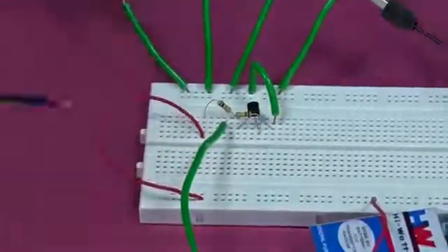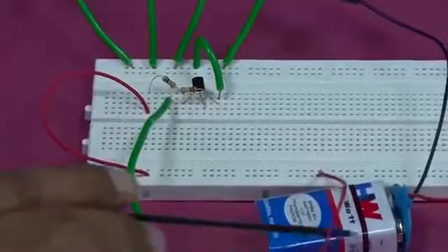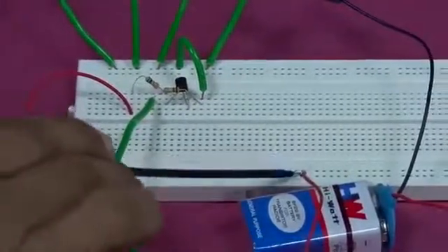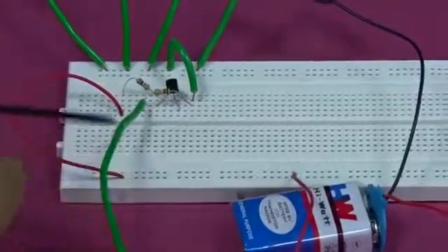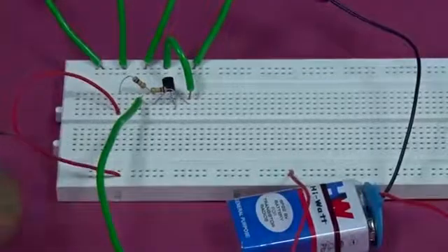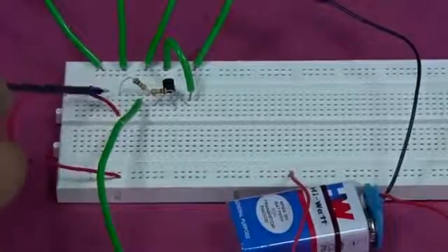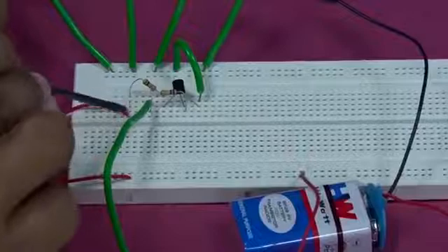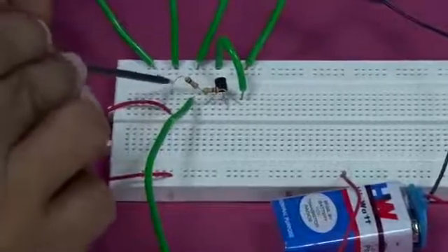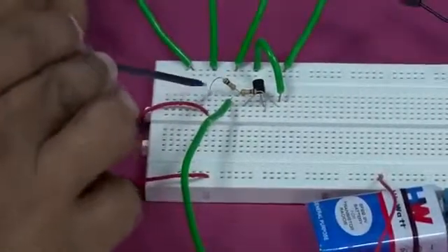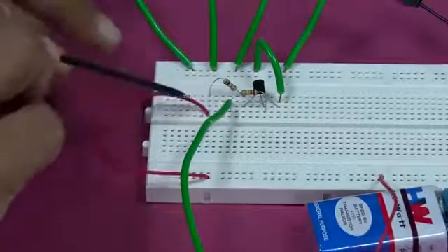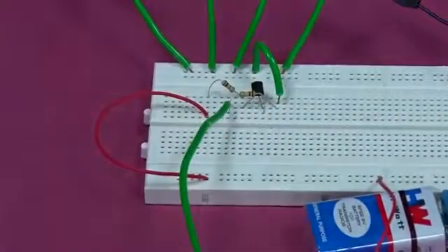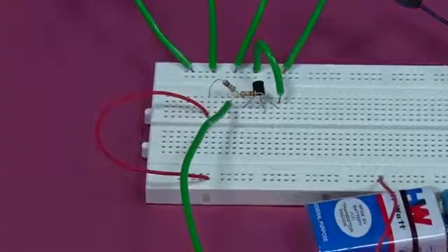So, you understand the working of the breadboard. The positive of the battery is joined here, but these are all internally connected. So, that 9 volt which is here is also coming here, and from here I am going to this point, and these ones are internally connected. So, this 9 volt has been connected to the other end of the resistance. One end of the resistor is already connected to the collector. That part is done. The negative of the battery is already at ground. So, our output side is also complete.